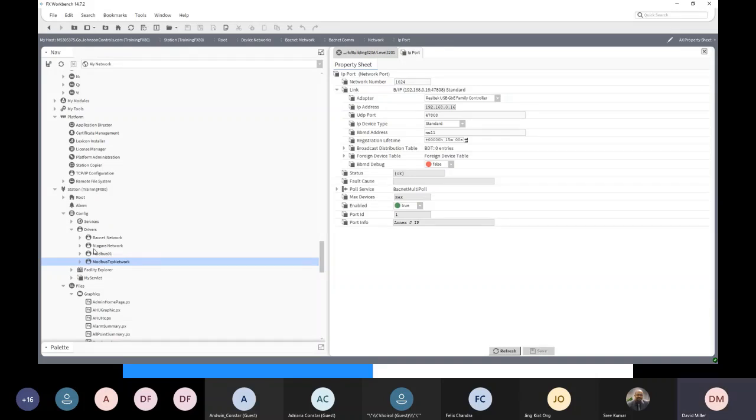Down at the FX80 level, you have to have the device licenses to cover all of the things that you've connected to. Whether you connected through a COM port or through the IP port, whatever you've connected to, you've got to have a device license for every device and enough points to cover the total points that you've mapped through those field devices.